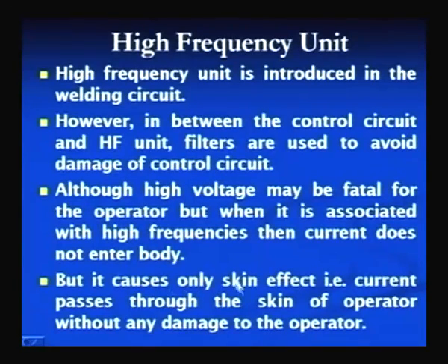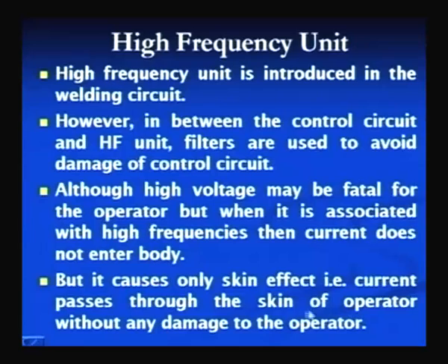Because of the skin effect, the voltage may be very high, but when it is associated with high frequency, it results only in the skin effect, meaning the current mainly passes through the skin of the human being and does not pass through the body of the operator, and that is why the operator does not feel any kind of damage or electric shock. So, the high frequency unit supplies the high voltage mainly to initiate the arc, and its association with the high frequency helps to avoid any shock related damage to the operator, which offers the benefit of the skin effect.